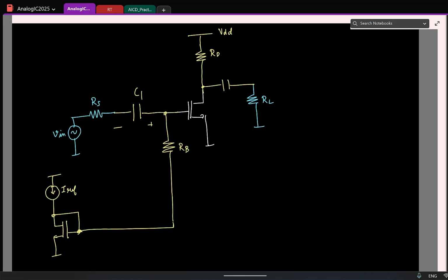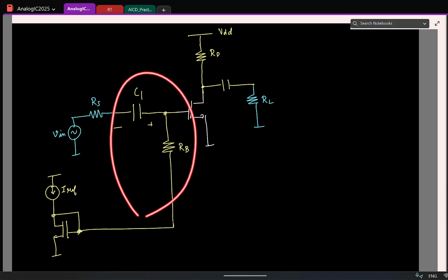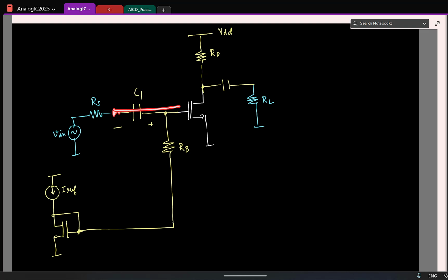So you can remember, anytime I give you an AC signal and a DC signal, this is how you bias it. Think of it this way: I can't connect the small signal directly. You have to shift it by a DC voltage. So in principle, you try to put a DC voltage source, but then you replace the DC voltage source by a sufficiently large capacitor, and make sure that the capacitor is charged to that required DC voltage. So this way you don't have to remember anything. Understand what we are doing.